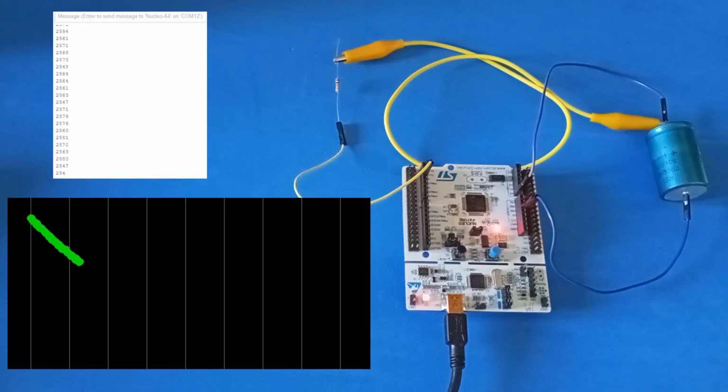Initially, pin D2 is set to low, slowly discharging the electrolytic capacitor as shown in the graph. At this stage, the onboard LED is off. Once the capacitor's voltage reaches 1 volt, it starts charging to 2 volts. The charging process is indicated by the onboard LED lighting up.